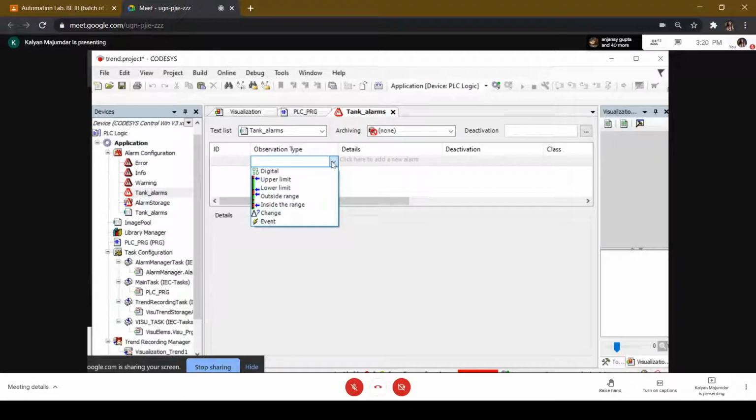One of them is a normal state. The other is an abnormal state where you want to generate an alarm. If you want to associate an alarm with one of the states of a Boolean variable, it's called a digital alarm. The variable has 2 states: one is normal, the other abnormal, and you want to highlight that by generating an alarm. In our case, overload is an example of a digital alarm because the overload sensor has only two states.